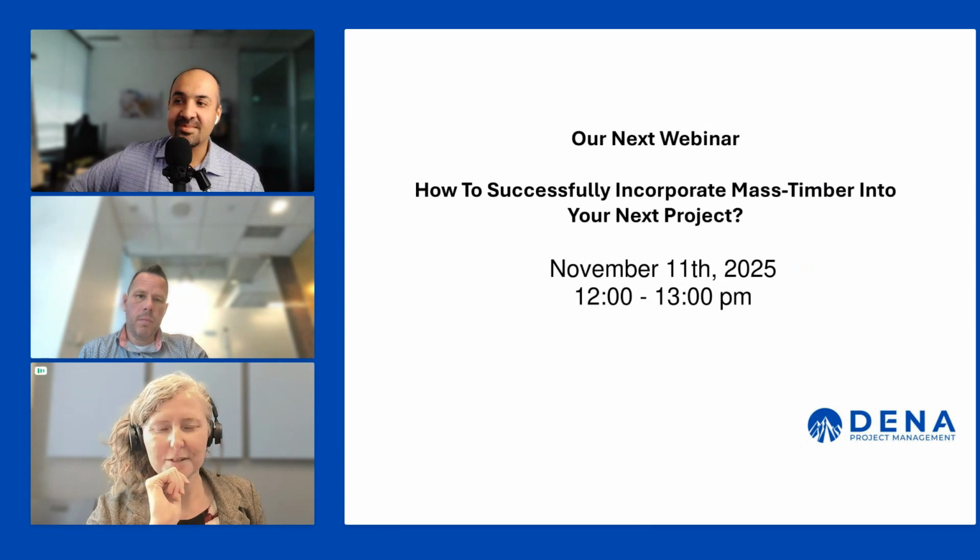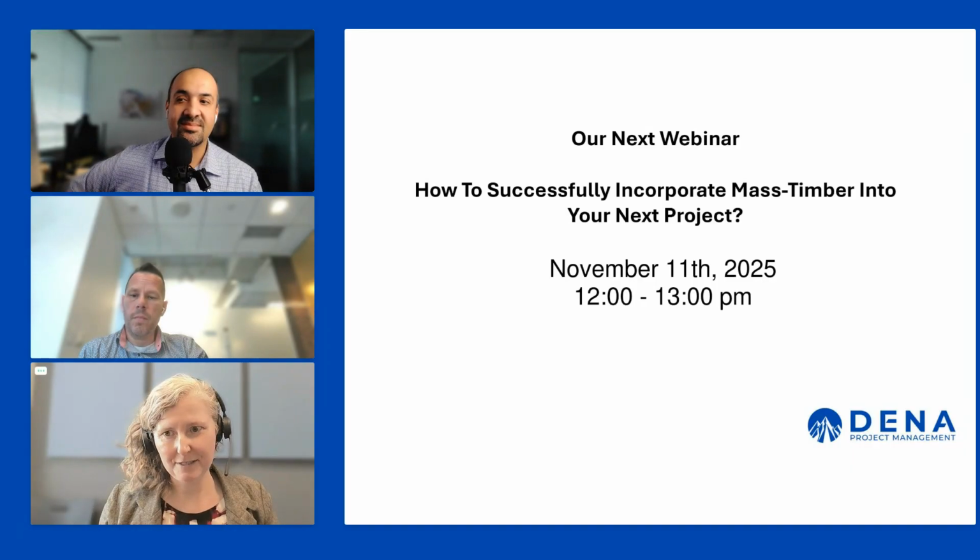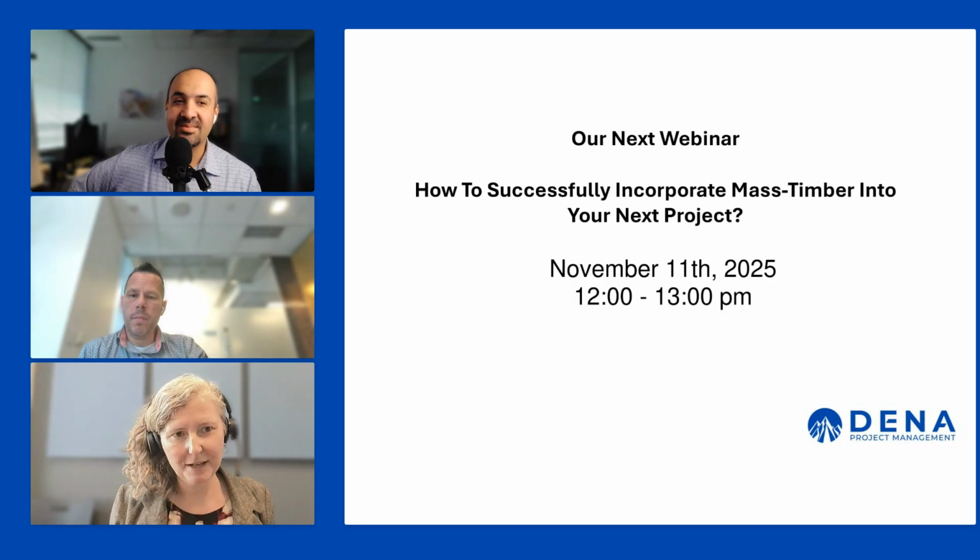I do see a great question about open loop geothermal, which is a very cost-effective way to do geothermal in your project. So when you work with your geothermal specialists on any project, they will be able to identify whether there could be an aquifer under your project. And the next step that's important when you're working with a geothermal expert is to drill a test well below the project to double check what the thermal heat transfer would be through the material below your building.